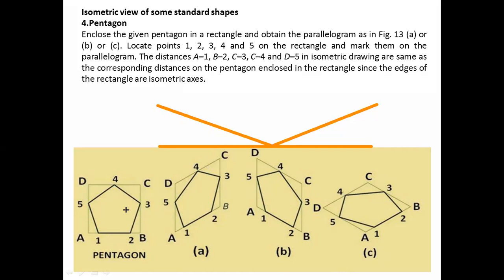Now, see, first of all, you draw this pentagon. You know how to draw that pentagon. Then out of that pentagon, what do you draw? You draw this line from its base. Just wait a moment. So you draw this line. Then from this point, draw a vertical line. Like this, and draw a horizontal line from this point. So ultimately you got the dimension of this square. So this parallelogram A, B, C, D we now got. So first of all we will generate that parallelogram here.